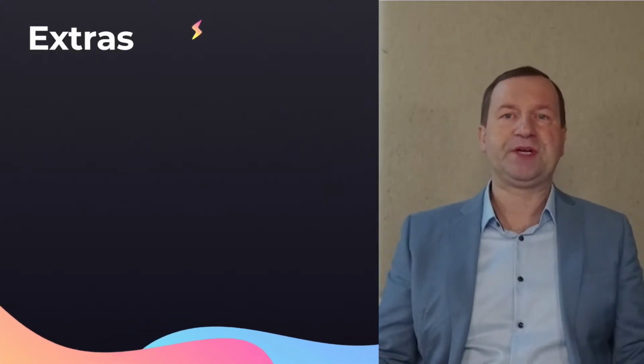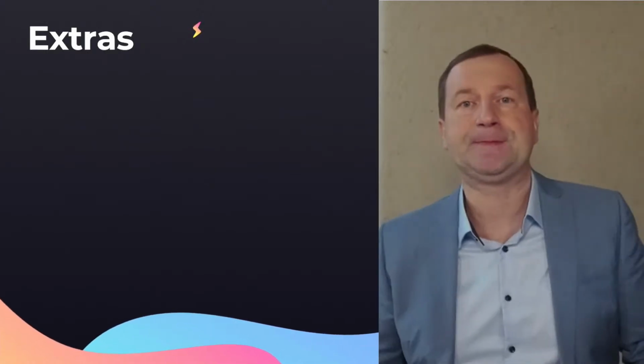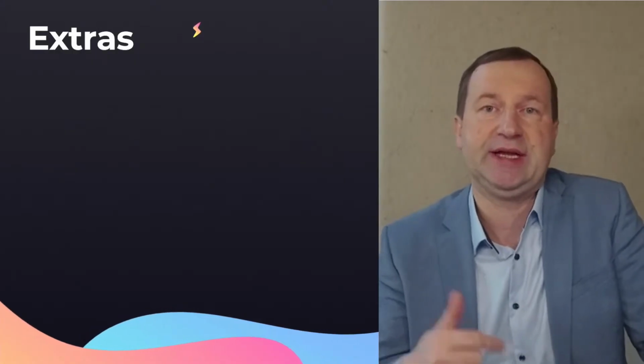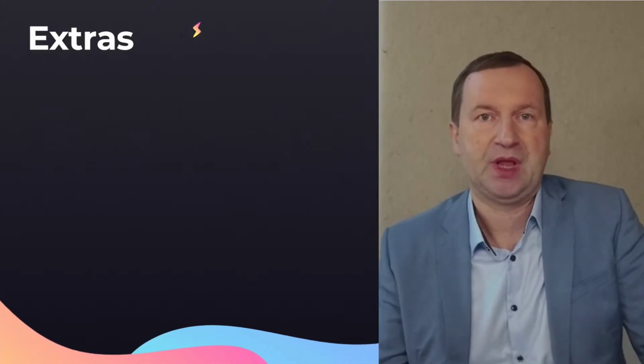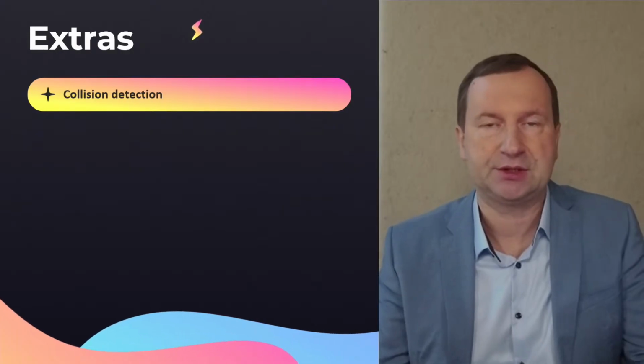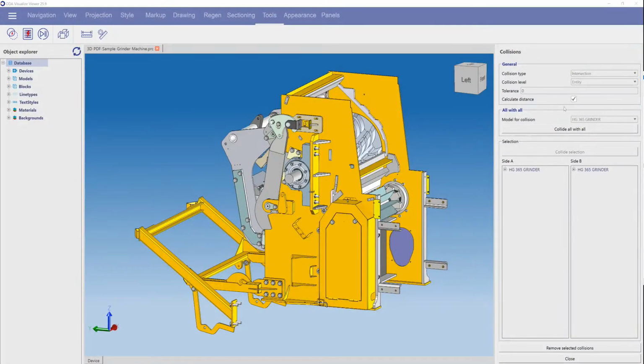To complete this brief overview of Visualize SDK, we'd like to highlight two features that at first glance may seem unrelated to rendering, but could be valuable to users. The first is collision detection. Collision detection is a popular feature in engineering applications. For example, it allows users to check a building model for potential conflict between parts that should not intersect, such as electrical and plumbing components.